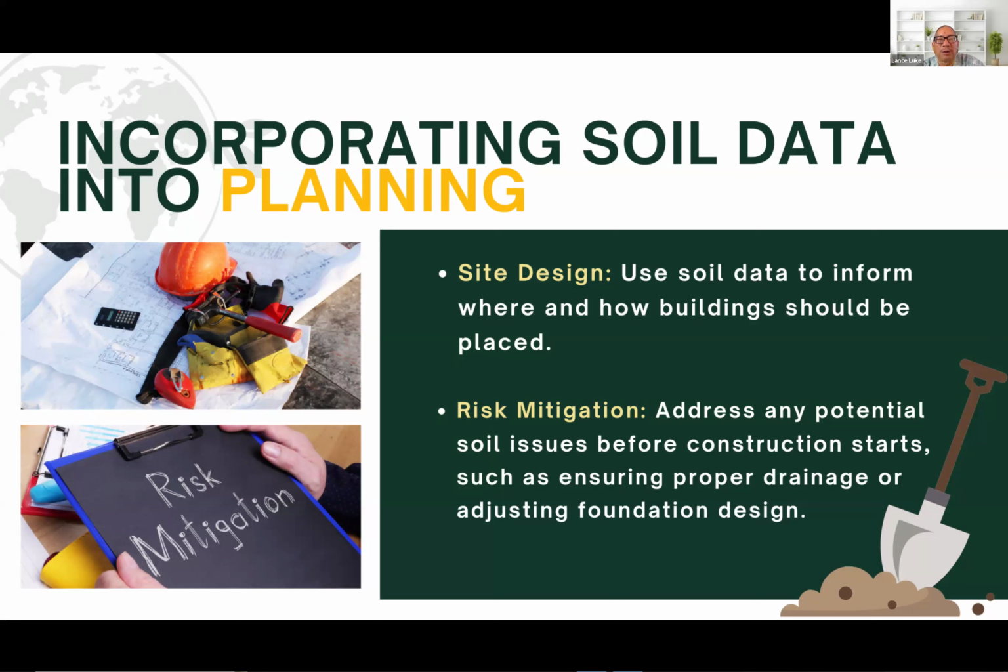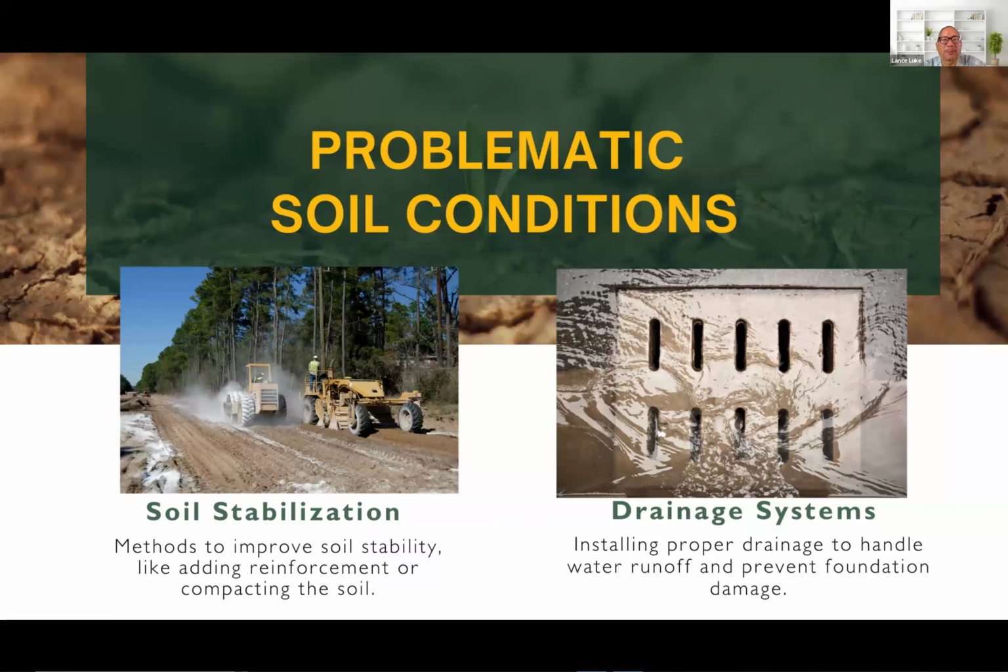Sometimes, due to the soil investigation and soil test results, the structural engineer has to change his foundation design to accommodate the information that was derived from the soil study. And sometimes the developers have to pay extra because these are unknown situations. Problematic soil conditions.